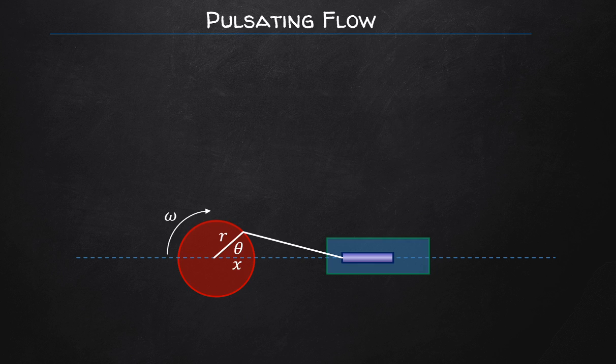And one of them, for example, was operating at 19% of its design efficiency. In other words, 19% of the time it was hitting the set point. The rest of the time it was fluctuating over the set point and under the set point. And so we need to account for these abnormal operations. They can come from the pump, but they can also come from changes in heights of the level, or the process controller changed set point upstream and it has a ripple effect downstream.